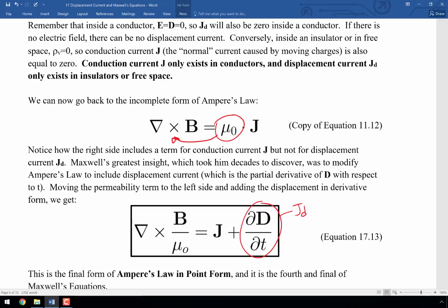And we can think of it as two different currents, that when you get to the boundary of a capacitor, over here we have J sub c, or just J as we're moving from left to right. In between, now you could think of it as being J sub d, and then when we get back over to here, we get J sub c again. So it actually allows us to think of it as sort of a continuity of the current density as well.